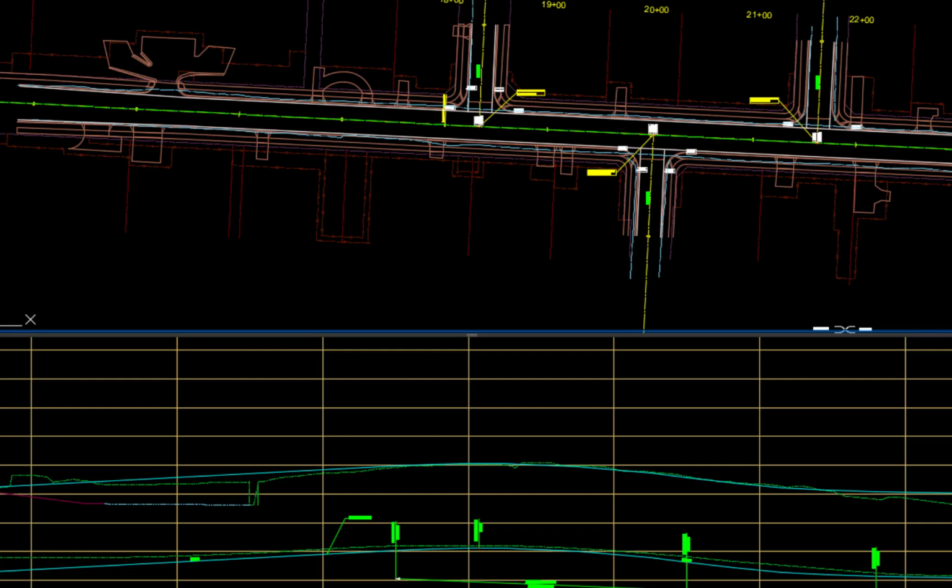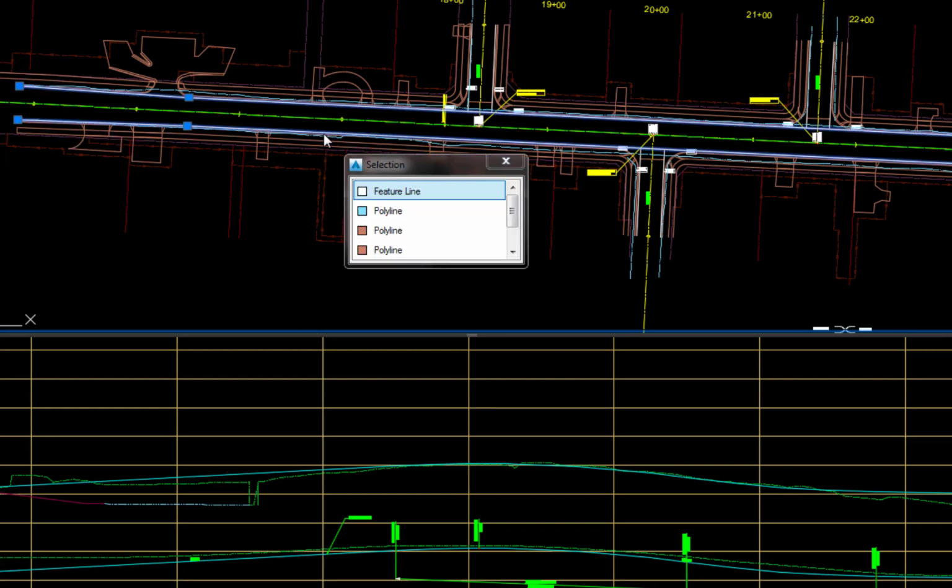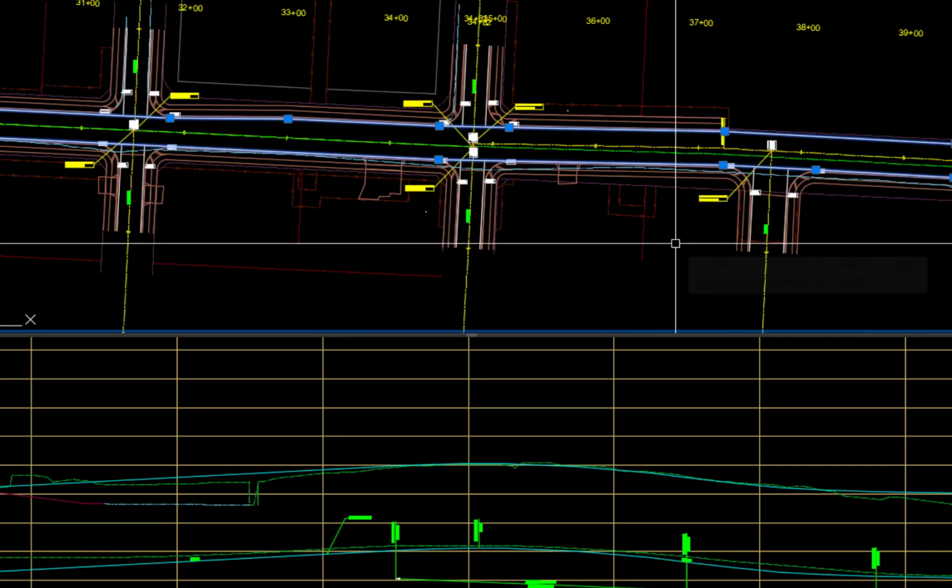The monitor shows two viewports with a plan view on top and the profile view on the bottom. Add temporary ETW alignment offset elevation labels in plan view at ETW angle points where the offset distance varies from the normal 14 feet. Pick the ETWs to see the location of angle points. Annotate ribbon.